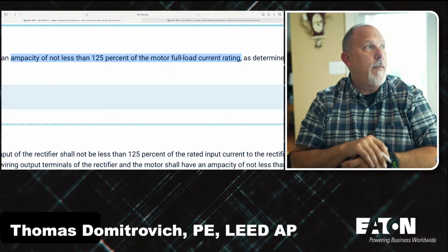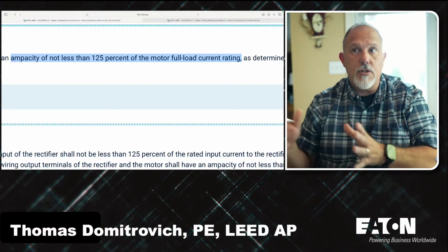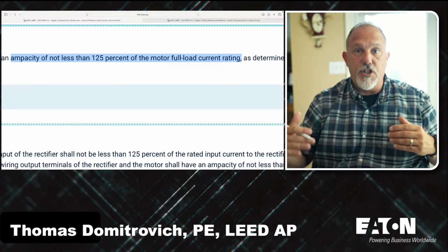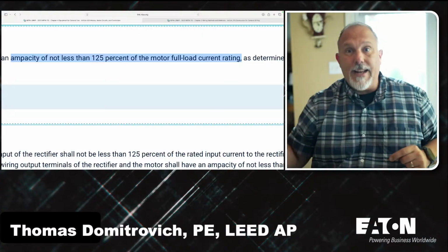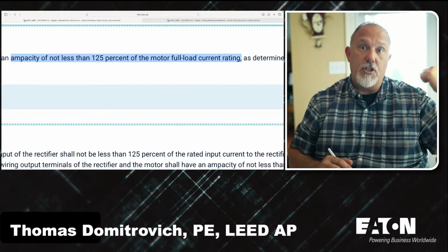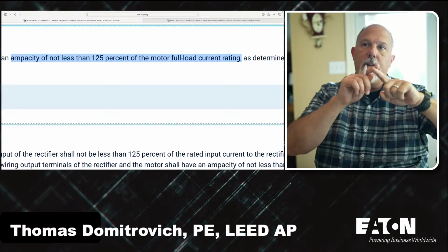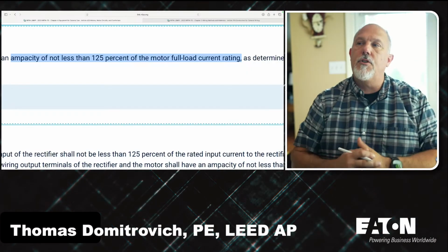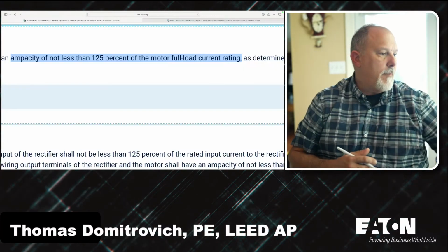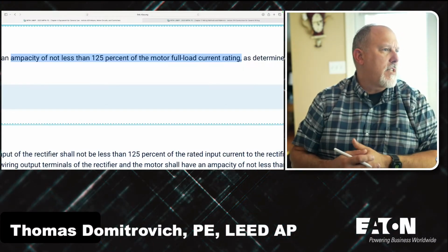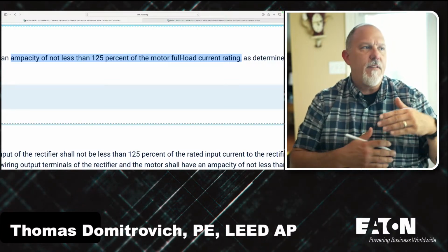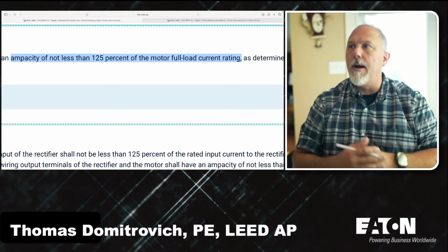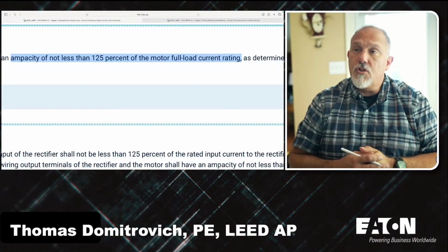Voltage drop could be one that is not driven by conditions of use. It's the length of that conductor that's driving the voltage down. Or it could be that my starting voltage is low enough that my length of conductor is driving my voltage at my motor terminals too low. But these motors are 460 volts, so if I'm on a 480 volt system, that 460 volts already accounts for the voltage drop. So I shouldn't have a voltage drop issue.